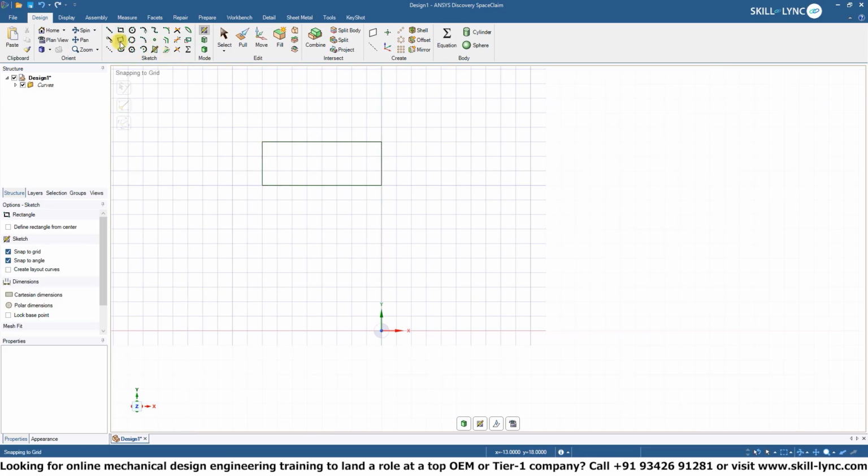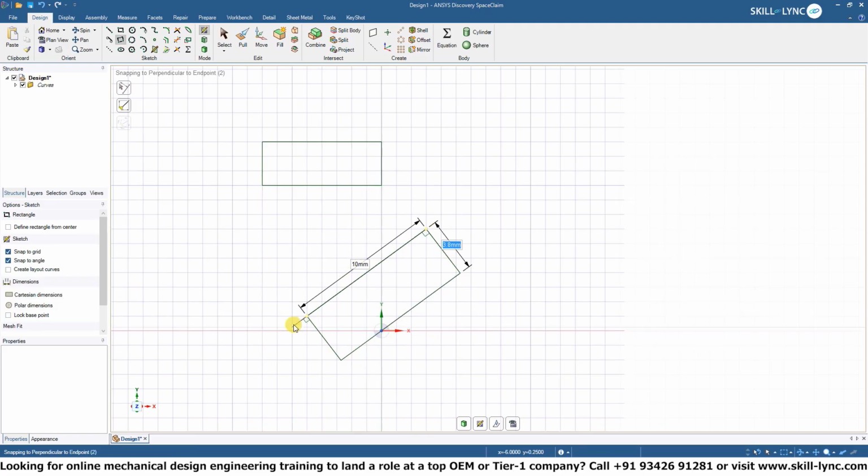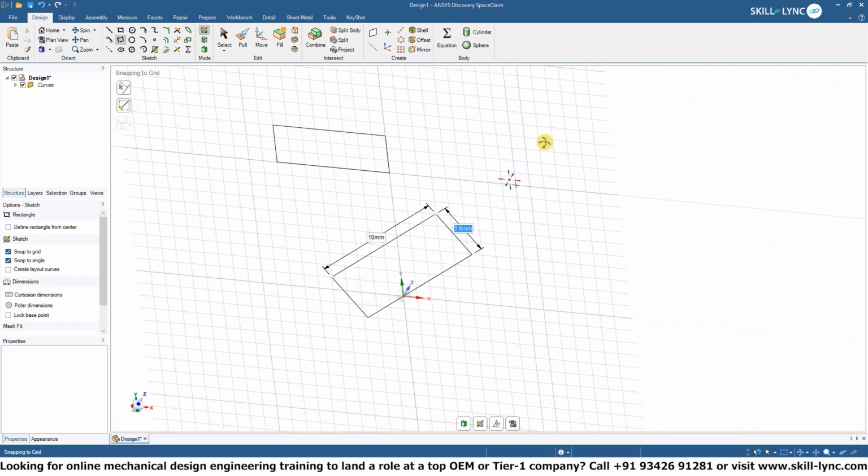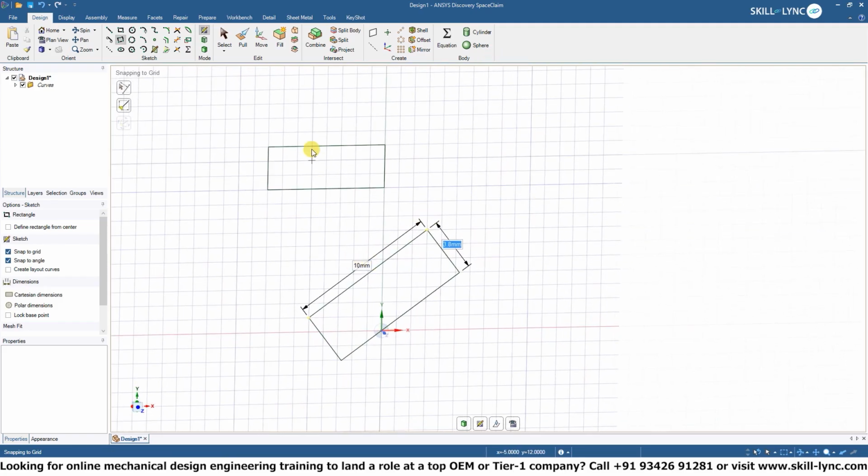But if you look closely over here for a 3-point rectangle, the rectangle is not straight, it's a bit skewed. So you can put the length diagonally, and then you can draw a rotated rectangle over here. See? So this can give you a few more interesting options to work with in your design or modeling.